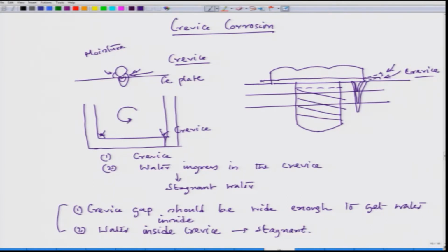For example, in this case, if we have dirt on the bottom of the steel container, it is always better to get rid of it. For a water container, it is better to clean it from time to time, and the cleaning allows the dirt particles to be removed, which finally reduces the crevice attack.